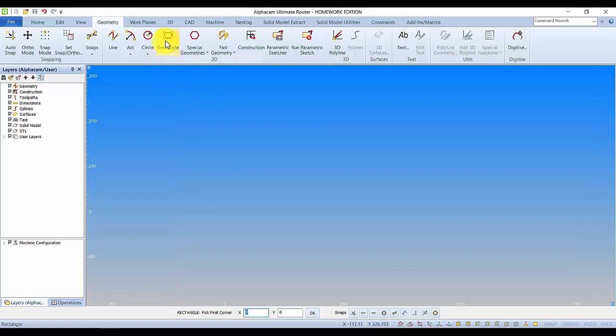So with the rectangle command, I'm going to start off with the first point being 100, tab 0, enter. And pay attention to where that first point has started. It's on the ground essentially. It's horizontally aligned from 0, but it's 100 mil tucked in from 0 in the x direction.